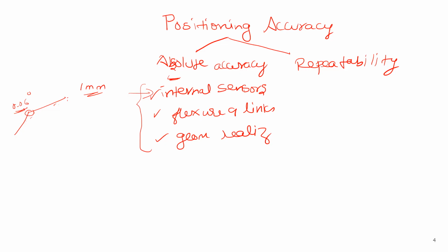Also, the next important thing is that during the high velocity motions of the manipulator, it will experience several forces, that is inertial forces, Coriolis forces, centrifugal forces. These forces make the control of the robot even more complex, right? So these inertial forces, as we have seen in the earlier sessions also, will vary with the square of the length of the link.